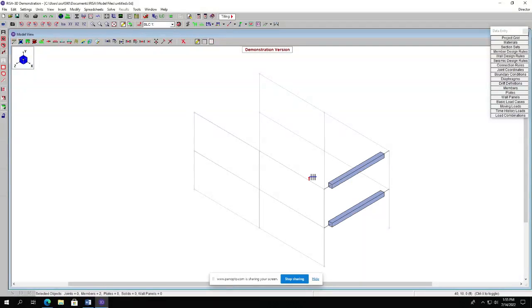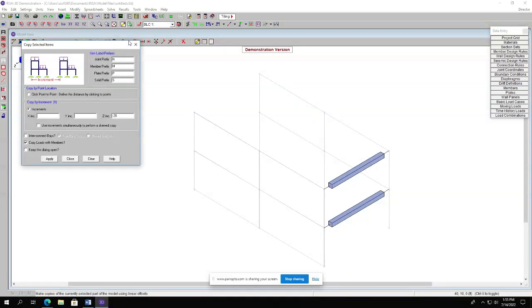This is selected. Now this needs to be copied as well, right? This needs to be copied to the other grids. So again, go through, make the copies of selected, and then go to x increments. We need 2 and hit -20, right? Is that correct?